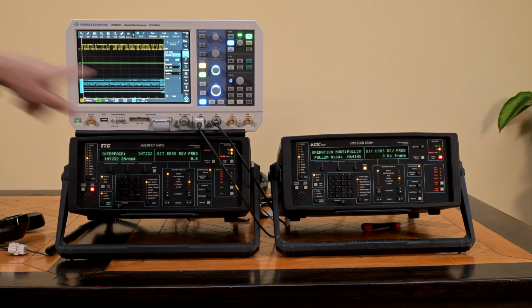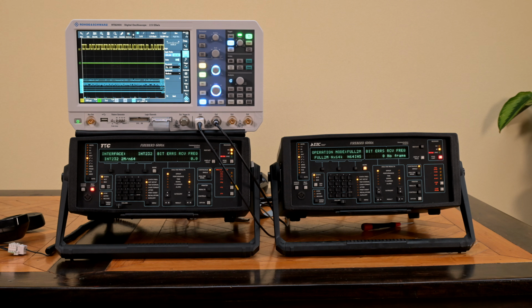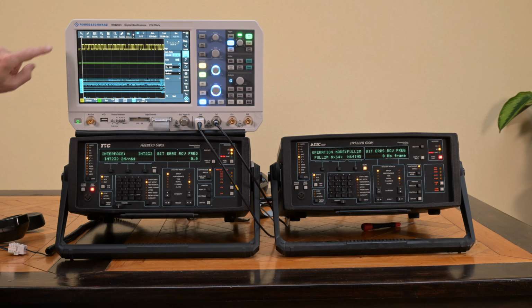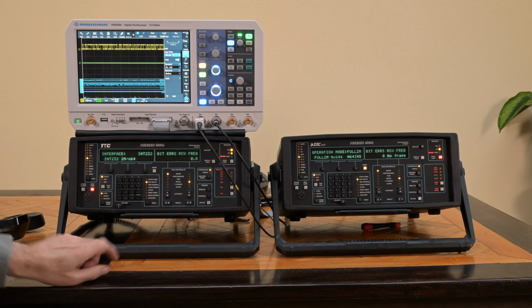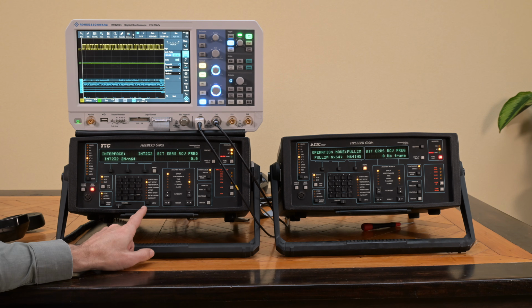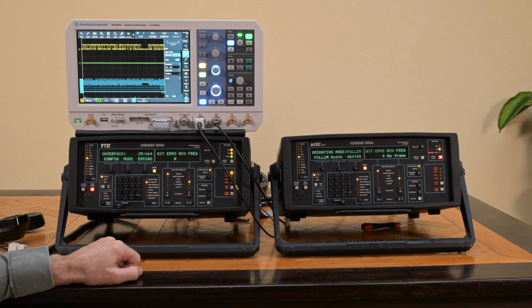And I've connected both units with a coaxial cable, and that's a 75 ohm cable, because that is how European trunks, E1 trunks, are defined. Now, the unit is currently running. I see the data signal and I also see all the test pins here, but I'm currently still running on the internal RS232 interface. So I'm going to move away from that one. I'm going to choose the European trunk line interface.